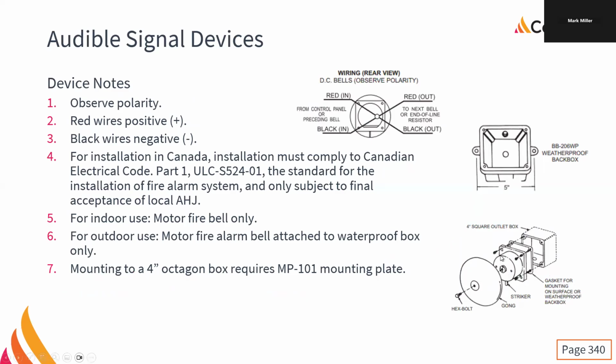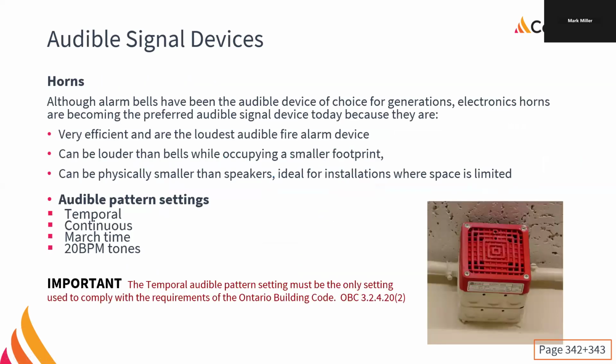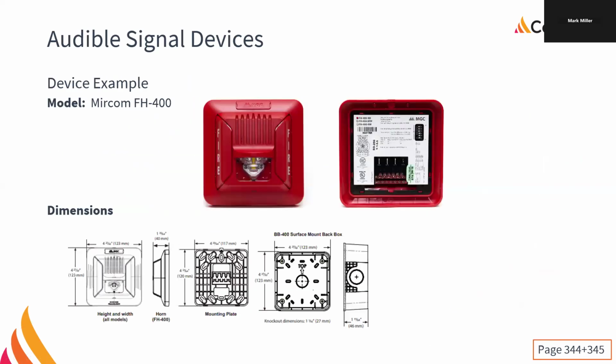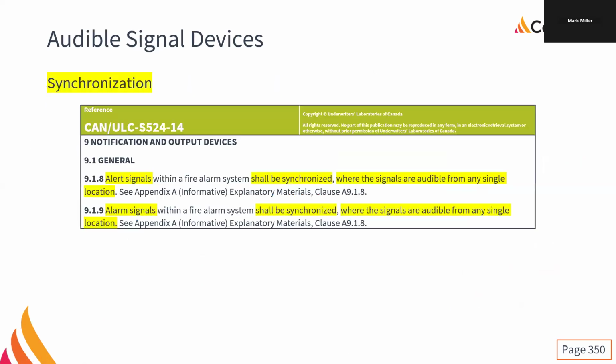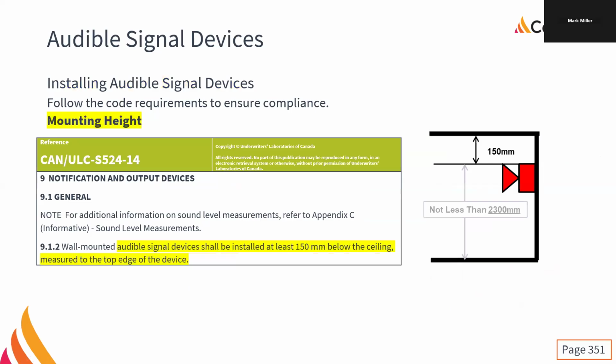There's just an additional bracket for the mounting. So if we have 10-inch bells, the boxes have to be mounted lower. So we have to be very careful with our mounting heights so that we don't have things mounted too high or too low. We absolutely want to know what type of device and what size of device we're installing before we add the boxes to the wall.